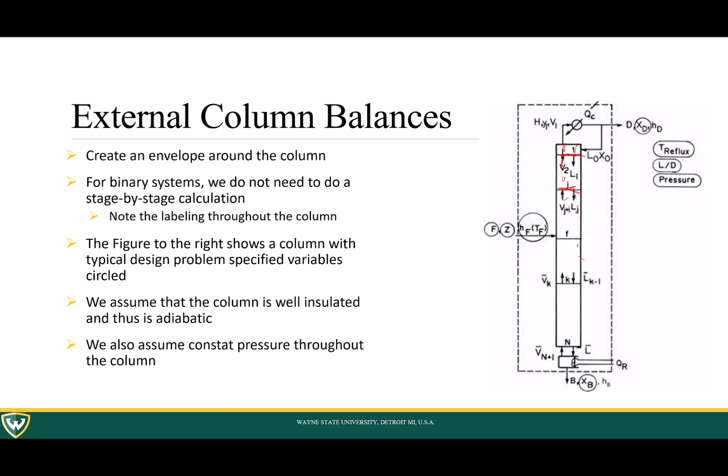One thing I want to note is the labeling. That's pretty important. So when you are in the enriching column or above the feed, note how your V and your L are just written as V and L. Okay, the subscripts, I wouldn't worry too much about it. But you do have one starting from the top. So you have V and then you have L. Below the feed line, below where the feed gets entered, you have V bar and L bar. That's to denote that this is below the feed line, okay? That's actually pretty important.